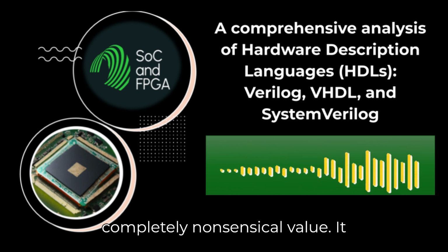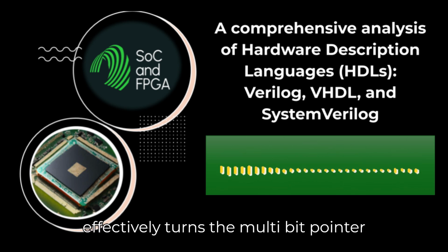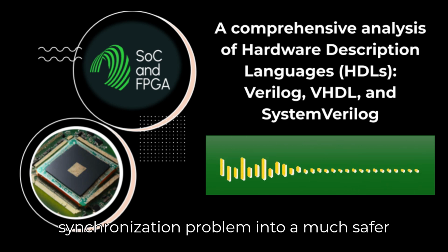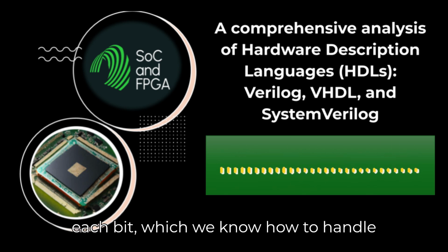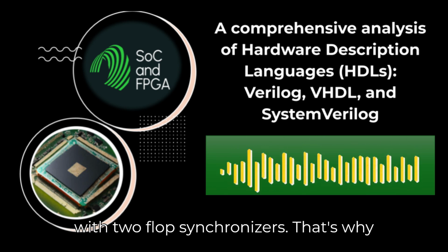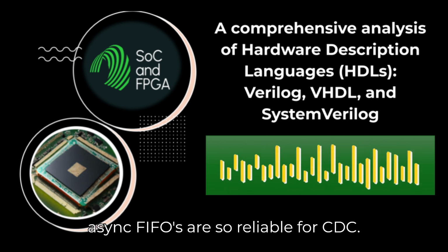You never read a completely nonsensical value. It effectively turns the multi-bit pointer synchronization problem into a much safer single-bit synchronization problem for each bit, which we know how to handle with two-flop synchronizers. That's why async FIFOs are so reliable for CDC.